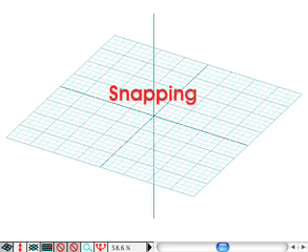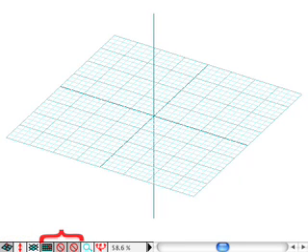Now that we have learned how to draw some basic shapes, we will move on to the second segment of this tutorial, looking at some other tools to assist you in controlling the cursor location when drawing shapes. This is called snapping. The snapping tools are located in the lower left corner of the Form Z window. The first 3 palettes on the left contain tools other than snapping and will not concern us here. The 4th, 5th, and 6th palettes contain 3 types of snapping tools.